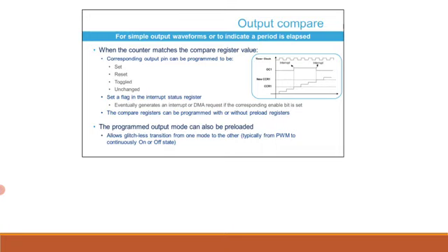The compare register can be preloaded. The preload must be disabled if multiple compare values must be written during a counting period. On the contrary, the use of preload mode must be preferred for applications with real-time constraints, since this gives a higher time margin for the software to update the compare register with the next value.